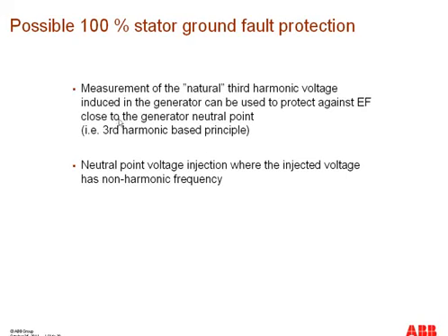No matter how good the generator is designed, the sinusoidal waveform generated will never be perfect, and there will be a third harmonic present in the winding in any case. So that harmonic voltage is taken as a criterion to protect the 100% stator winding.